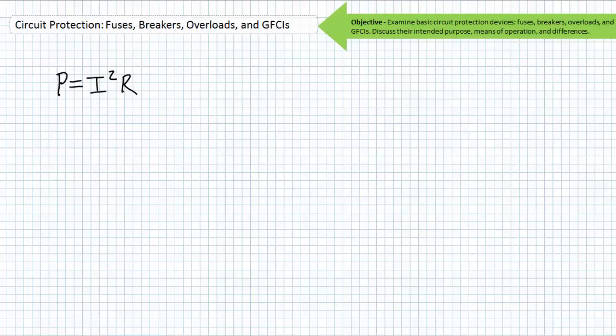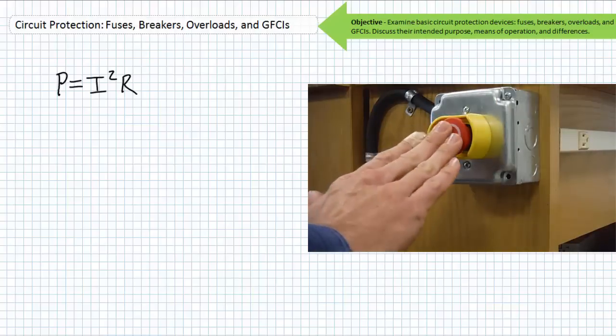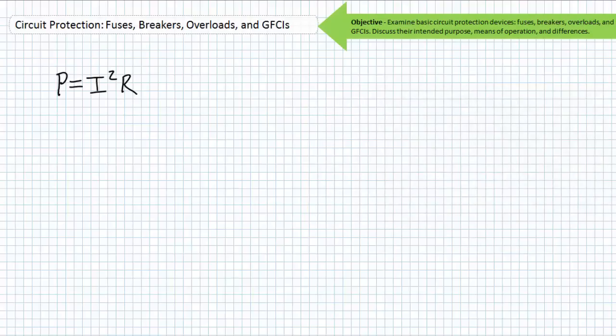Pay attention and be prepared to shut it down any moment you observe unusually high current for a sustained period of time, smell or see smoke, or worse yet, see flames shooting from the system you're working on. Know where the off button is and make sure you've got access to it. Industrial systems often have strategically placed emergency stop buttons that allow an individual observing an unsafe action or scenario to immediately disable the system. Familiarize yourself with the location of these switches and know their intended purpose.